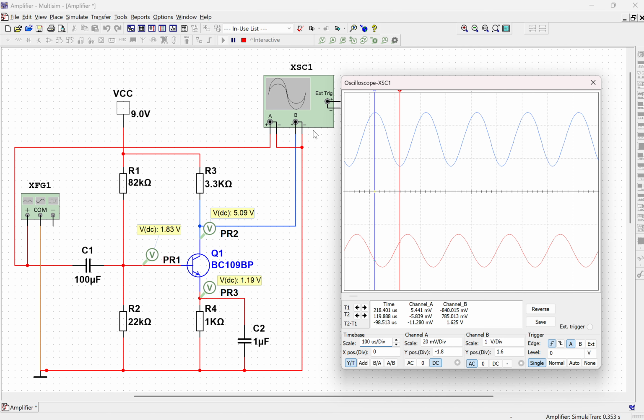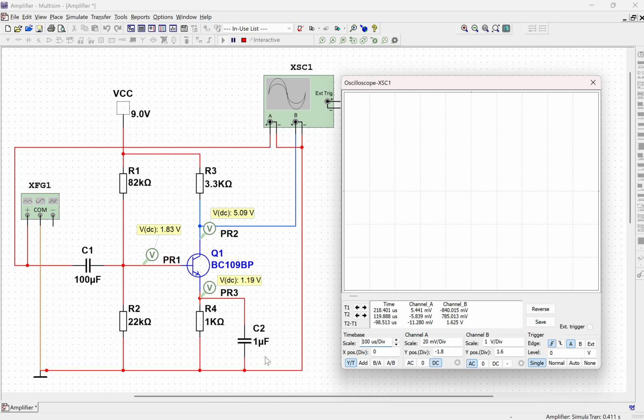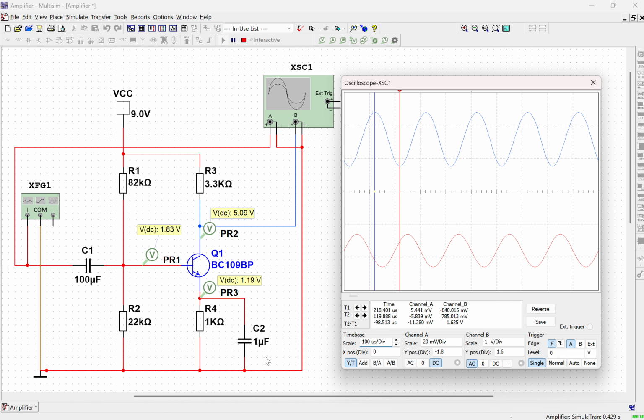I would recommend that you do some research with regards to what that capacitor does. Essentially it is separating AC and DC components, and you can also back this up with the theory by working out your capacitive reactance for different capacitor values using the 1/(2πfC) formula. That will back up your testing. Take screenshots, and then also document it in a report style in your assignment.